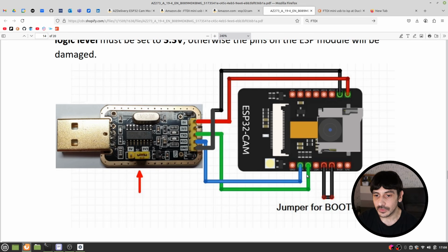And then moving to the data transmission part, you can see that we are connecting this pin over here with this one, which is TXD, and this other one to this other pin, which is RXD. So that's basically how to connect all the wires: these two wires have to do with the power supply, and these with the data transmission.